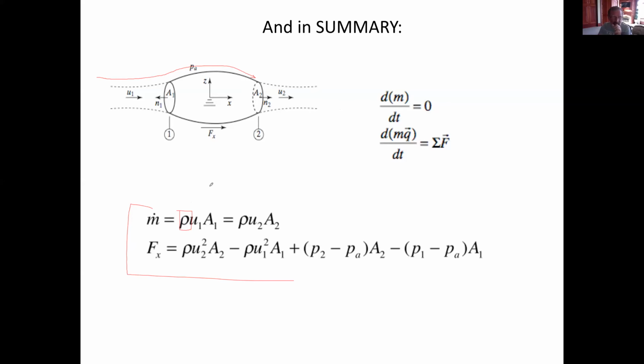In the case of gas, if I go back to this example, the flow really has to be like Mach 0.8, Mach 0.9 for the density of the fluid to change from here to here. Otherwise, it's not. So we can say that if the velocity is less than Mach 0.6, which is pretty fast, we can assume that rho is a constant. Okay, are we good so far? And actually, you can extend that model later on.